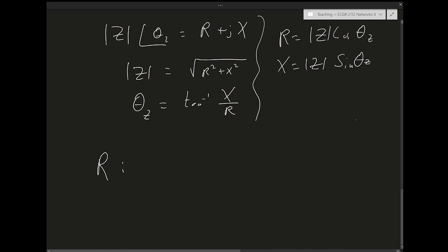When I take R, I apply a voltage to it, I get a current I through it, right? And we found out last time that V equals Ri. So that means that for R, remember Z is the ratio between V and I. So for R, Z is just R, the resistance. Z has a pure real component, and does not have an imaginary component.